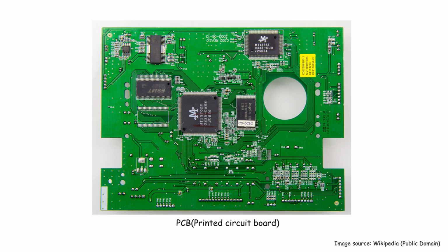But what happens if you discover an error after manufacturing? Say, a misplaced trace or component. In that case, to make a proper fix, you need to go back, revise the schematic and the layout, and manufacture the board again. Technically, you could cut a trace and solder a jumper wire as a patch, but doing that on commercial products would seriously reduce reliability. I'm using this contrast between breadboards and PCBs because it mirrors the difference between FPGAs and ASICs.